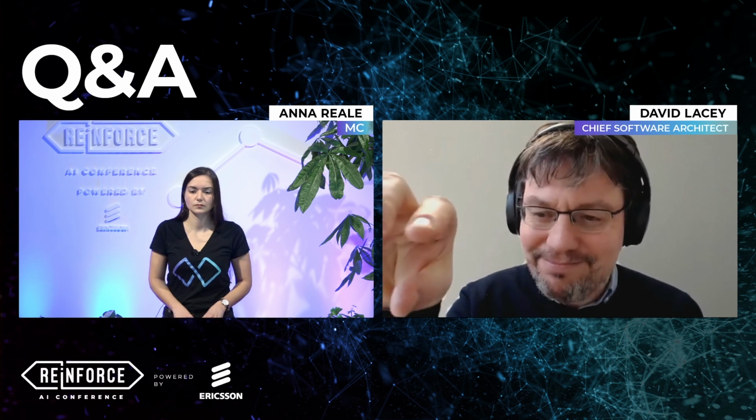One of the things that bodes well for Graphcore IPUs in terms of energy efficiency is the memory architecture. By putting a lot of memory on the chip, which has to be done fundamentally at the chip level and then built upwards, where the distances are very small, you don't spend as much energy moving data around, up to that 900 megabytes limit.